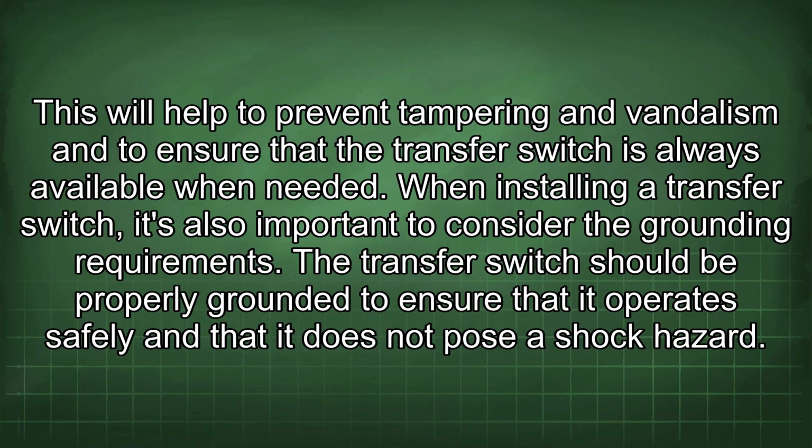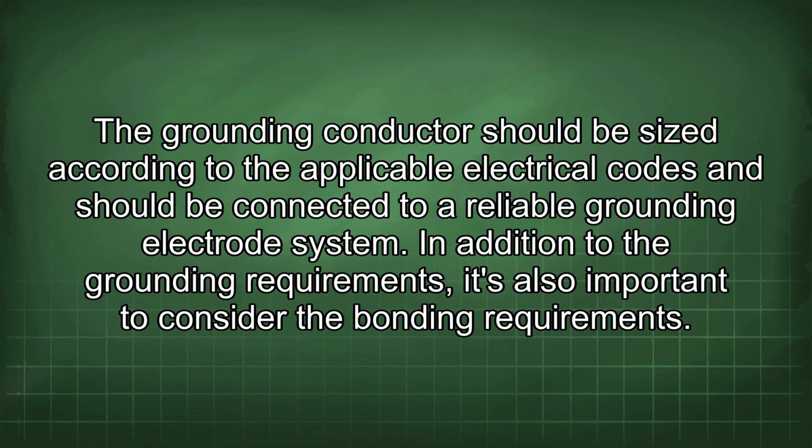When installing a transfer switch, it's also important to consider the grounding requirements. The transfer switch should be properly grounded to ensure that it operates safely and that it does not pose a shock hazard. The grounding conductor should be sized according to the applicable electrical codes and should be connected to a reliable grounding electrode system. In addition to the grounding requirements, it's also important to consider the bonding requirements.